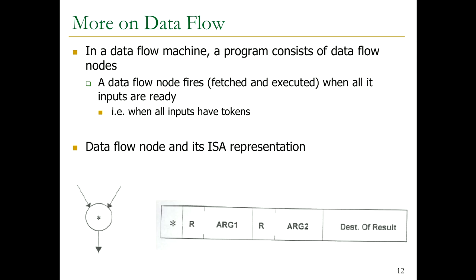In this case, you basically send it to some memory location and set that bit for the correct argument in the memory location. And when both bits are set, there's some logic that checks, that's the matching logic, whether both bits are set. If both bits are set for your own operands, you can fire. Does that make sense? If you didn't understand it, that's okay. We'll talk about one implementation of it in out-of-order engines.